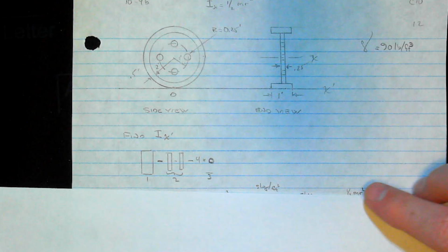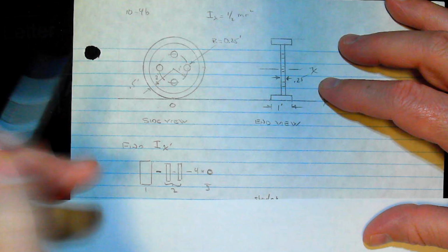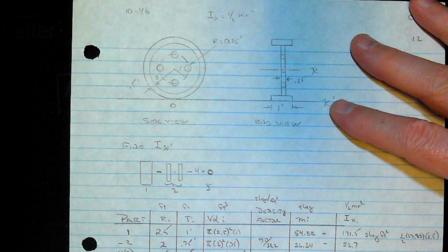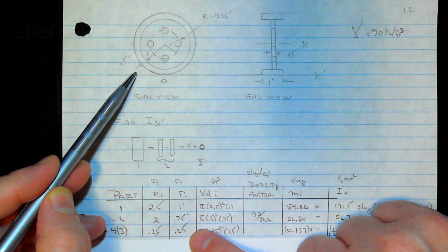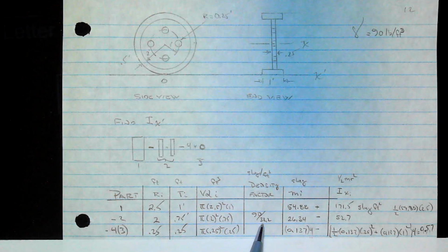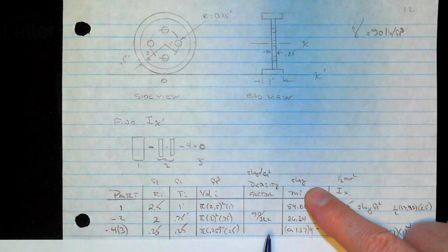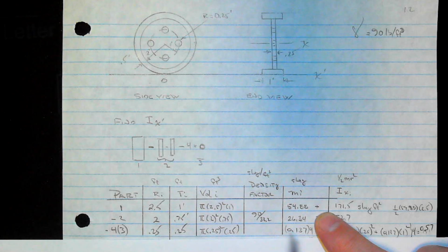All right, so let's think what we're going to need to do this. Cone volumes. Why do I need the volume? That made people maybe go, why am I doing that? Well, we need the volume of the cone because we don't have the mass of anything. We have the density of the cone. It's all one density, easy to handle, but for every one of these cones, I need to compute the volume, then I can multiply by the density to get the mass. This is mass moment of inertia, so I've got to get volume to get mass. No problem.